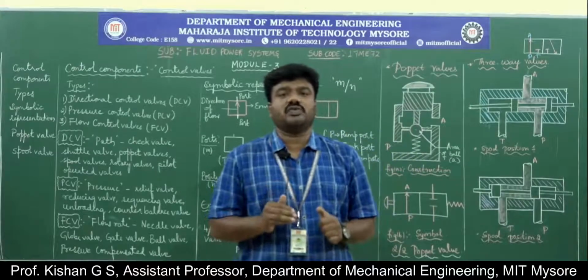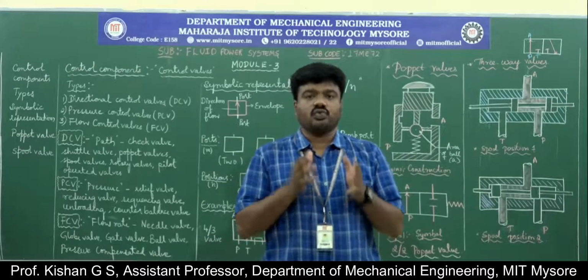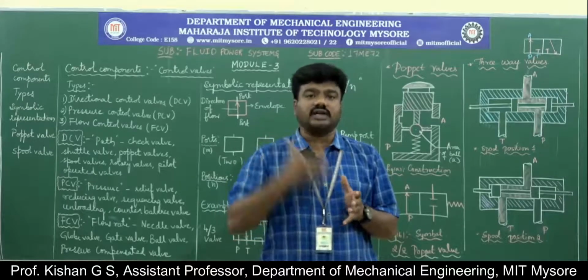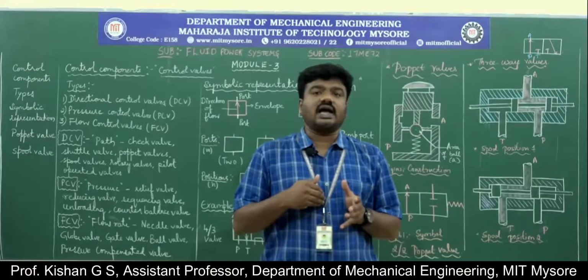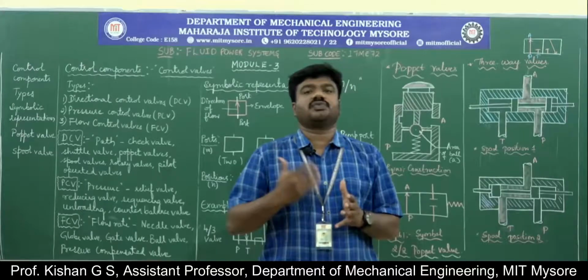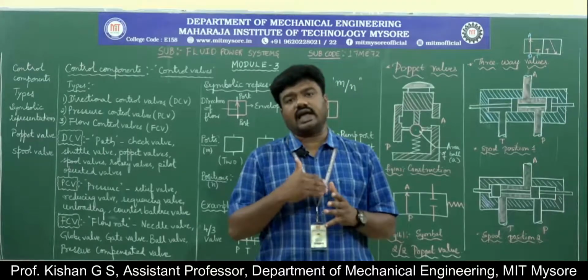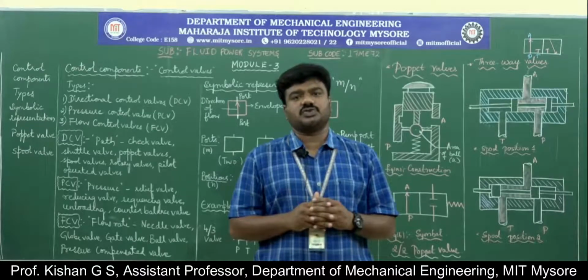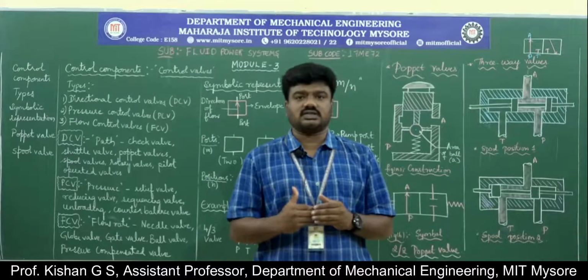The tank port is always a receiver end. Wherever we represent, there should always be a flow from any of the ports to the tank port, whereas from the tank port, you cannot directly allow the fluid to pass into any of the system ports. This is simple common sense that we have to remember for the next classes as well.